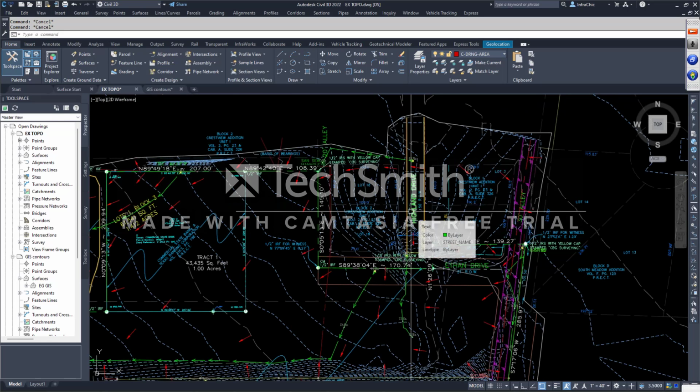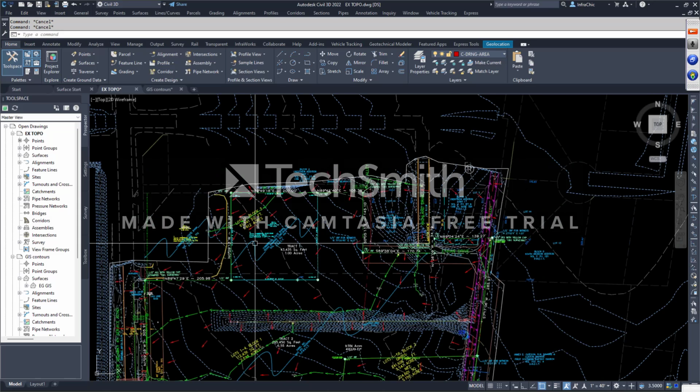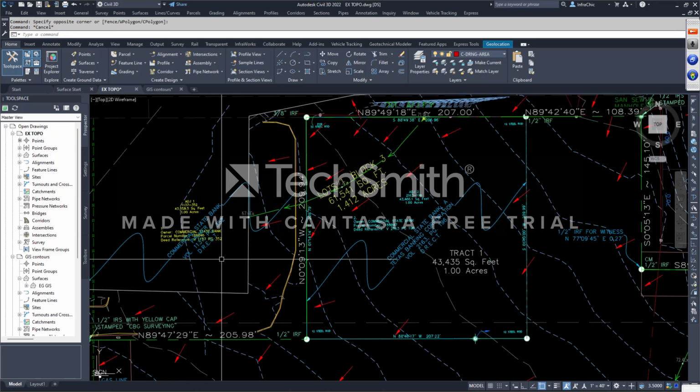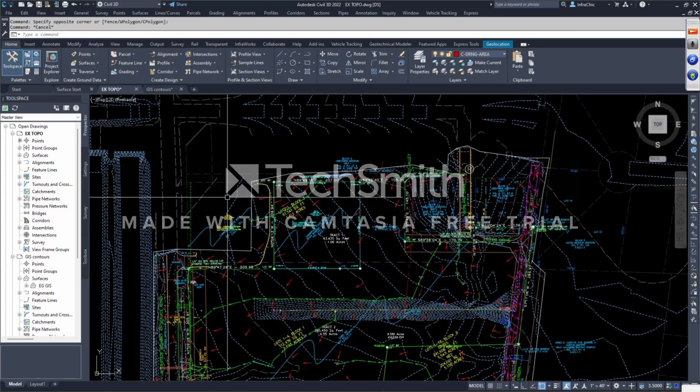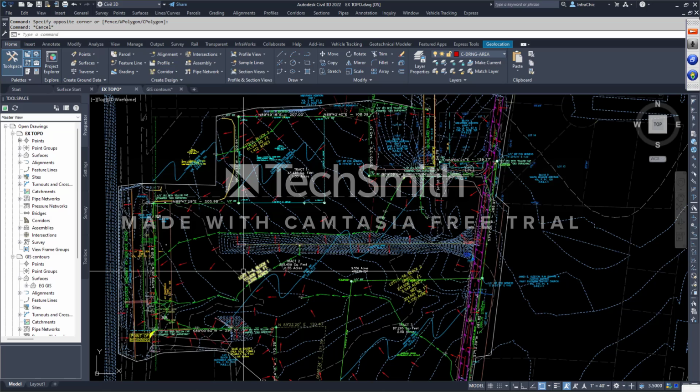So as a surveyor, and you're going through making your topo files, consider your existing file needs to display all this information for the civil, because the civil must show this in their files. Every little piece of it, even if it's what it was to what it is now, okay? They have to show all of it. The survey department of the city and county will actually review a civil's package to make sure that your survey matches what they have on file. So, but again, going back to surfaces.